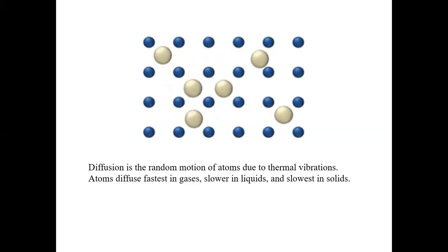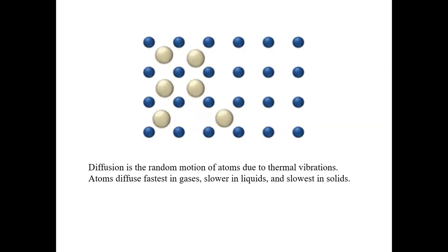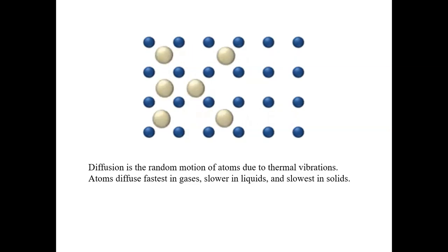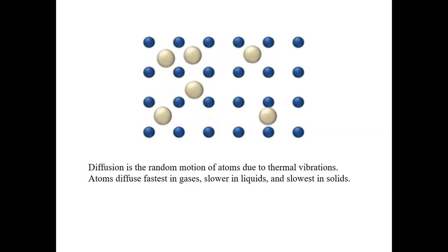And now what I show here, I will not say this is a better illustration, but I think it illustrates another aspect of interstitial diffusion. What you can see here is that we focus mainly on the white or silver particles, which are the interstitials. They're diffusing in a lattice of blue particles. One thing you can see is that these white particles are vibrating all the time. At some point, the vibration can suddenly get stronger, probably from receiving a phonon from the environment.